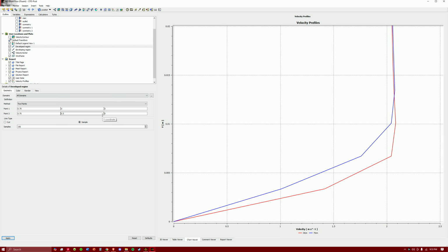So now you can see, you upgrade the samples. And if you actually up the samples even more, which I'm going to do, so we can get really accurate lines, you'll see how much they curve. There you go. You can actually see the velocity profile. This is what you would expect, because as it goes farther on the plate, the velocity profile develops more, which means it actually gets slower at the bottom because the boundary layer gets thicker. So you can see on velocities at the bottom, 75 is actually slower at higher points.